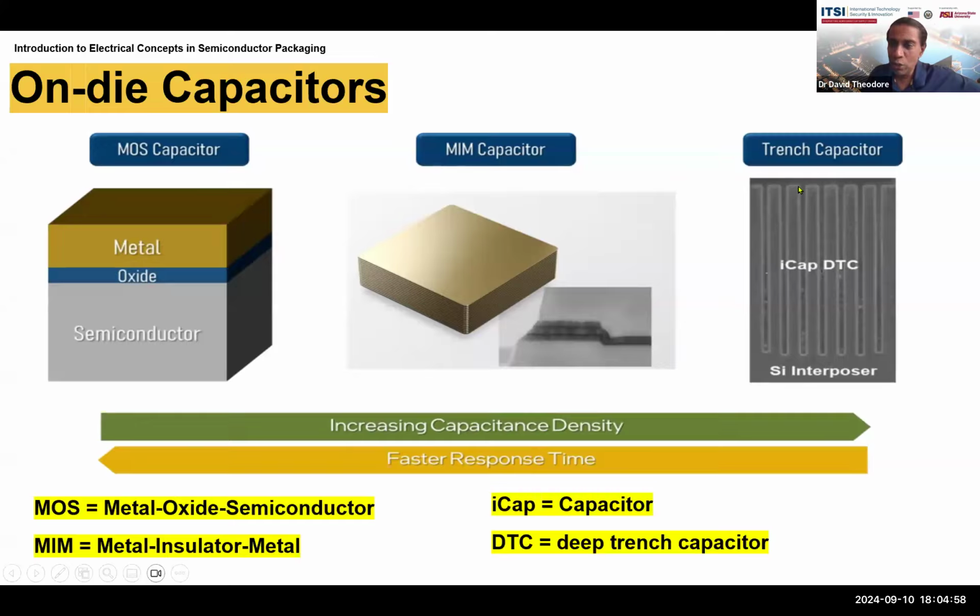Here, what you're doing is you etch a very deep trench. This trench can be 5 microns deep or deeper, and there's a small opening. In that trench, you deposit a thin oxide, typically as an insulator. Then you put a thin metal, then an insulator, and then another metal. Those go over this, and that can create a capacitor that has a large area inside a very small lateral form factor. That means you can increase the capacitance for a very small lateral space. That's the purpose of these.